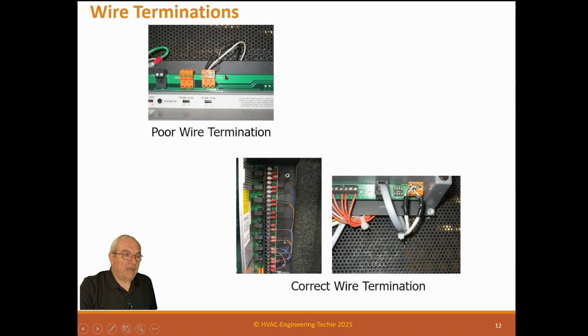Now, one thing about when you have ground loops and stuff like that, they're really hard to figure out. So just make a habit of doing good wiring practice so they can't happen, so you can figure it out easier. So this one here is a bunch of digital outputs. So these are done in just THN wire. These are not control cables like these, the conductors.